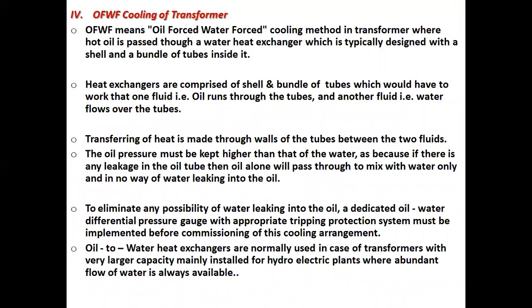OFWF cooling of transformer. OFWF means oil forced, water forced cooling method in transformer, where hot oil is passed through a water heat exchanger, which is typically designed with a shell and a bundle of tubes inside it. Heat exchangers are comprised of a shell and bundle of tubes, which work such that one fluid, that is oil, runs through the tubes and another fluid, that is water, flows over the tubes. Transferring the heat is made through the walls of the tubes between the two fluids.